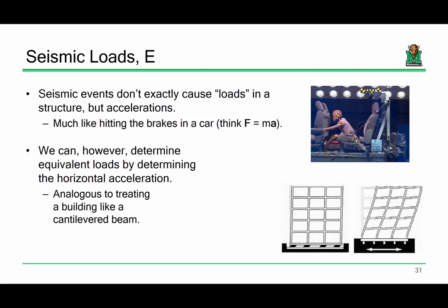With earthquakes, it's not some external force being applied to the building. It's basically a result of Newton's second law. Think force equals mass times acceleration. What does an earthquake do? An earthquake basically accelerates the ground. The ground is undergoing an acceleration, and that acceleration is being subjected to the building. So the way you get your force is mass times acceleration. The building is not light as a feather. It has some very significant weight to it. So force equals mass times acceleration.